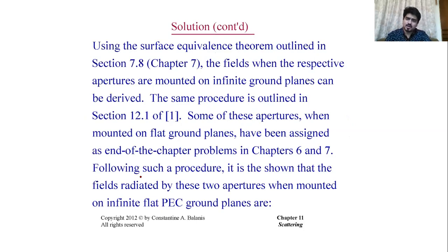Now we will compare those two solutions with the apertures when they are mounted on a flat infinite ground plane. We have gone through this practice in chapter 7, section 7.8 of the textbook, using the surface equivalent theorem.